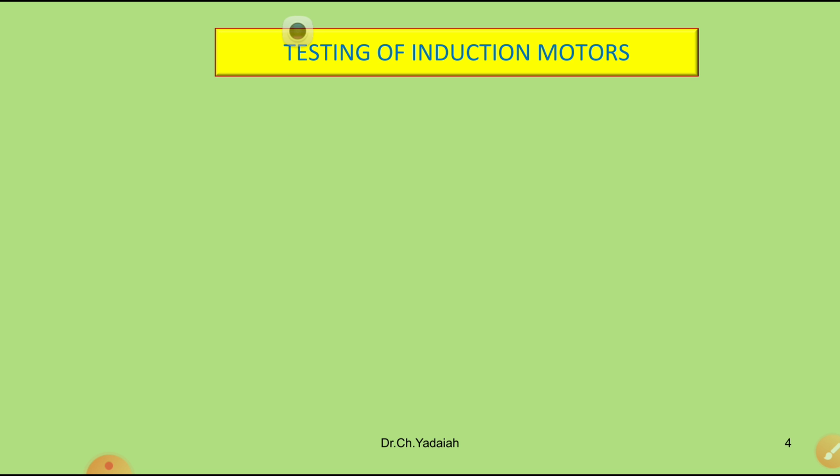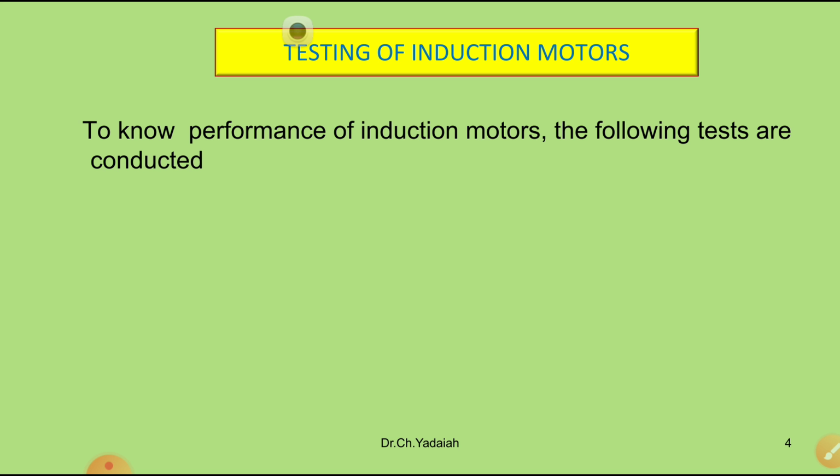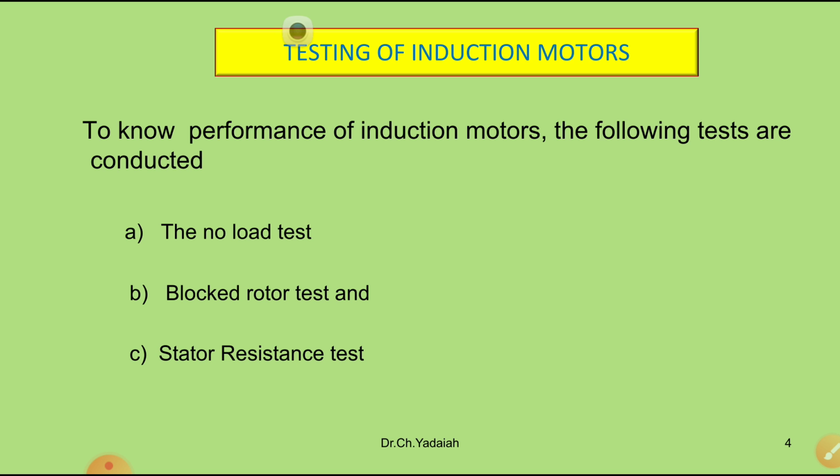Testing of induction motors. To know the performance of induction motors, the following tests are conducted. First one is the no load test. Second one is the blocked rotor test, and finally the stator resistance test. These three tests we are going to conduct in our laboratory also.